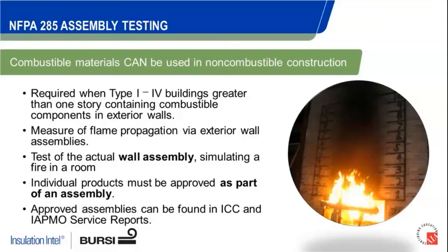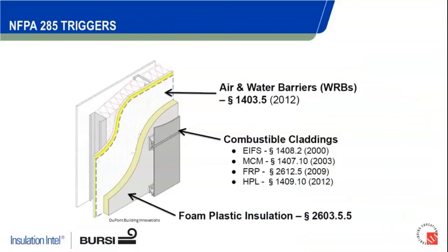Without getting too far into the nitty-gritty of that test, you can see there it simulates a fire at a window. The fire exposure runs for 30 minutes. And if we maintain certain parameters, both in flame spread and in temperature rise, that assembly with those combustible materials now passes that test and can be used in those Type 1 through 4 assemblies.